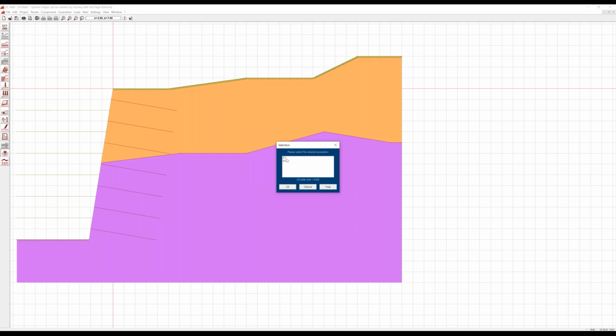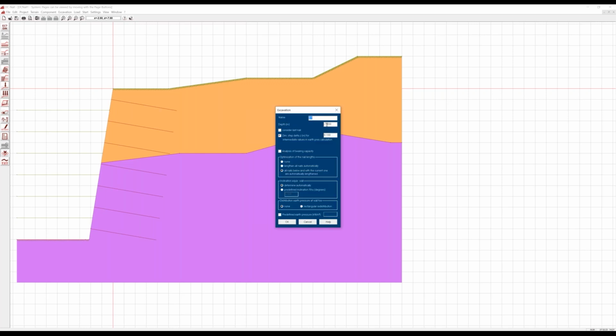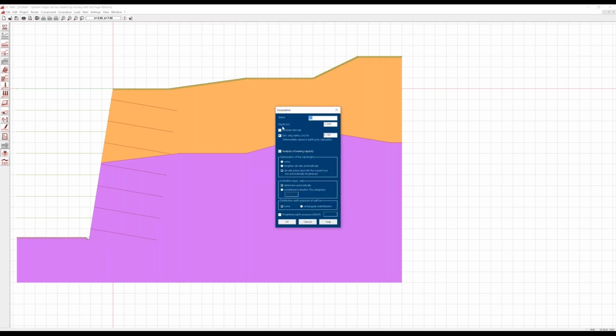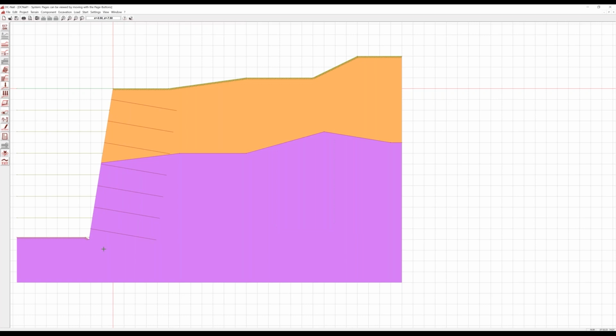And if I edit excavation stage 7, this should be a little higher, 6.9 meters, for example. And the last excavation stage, E8, should consider the last nail. So in this last stage, the last nail layer is present. So we have now 2 different stages.